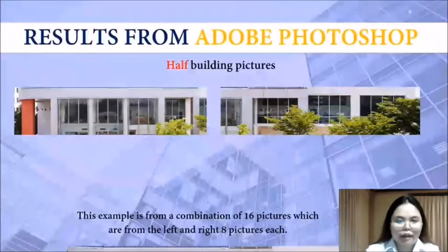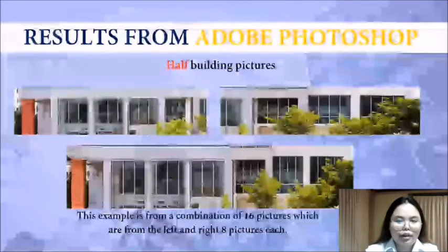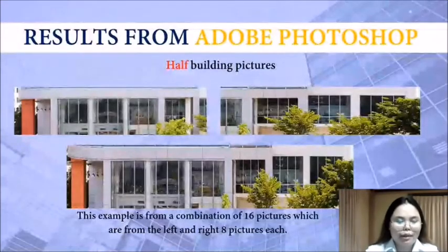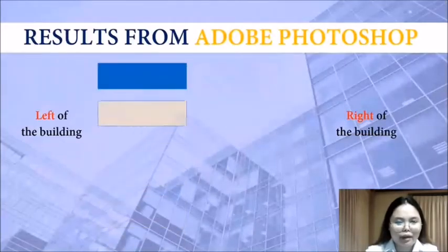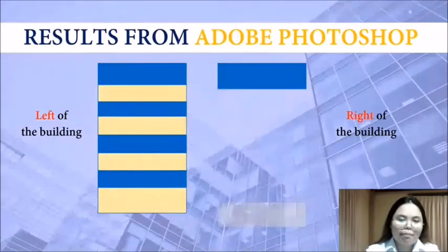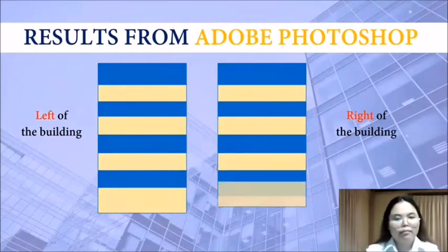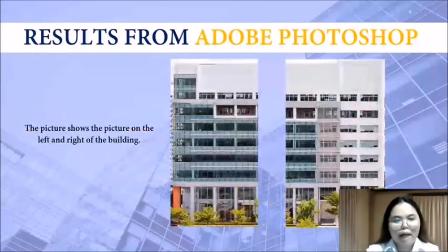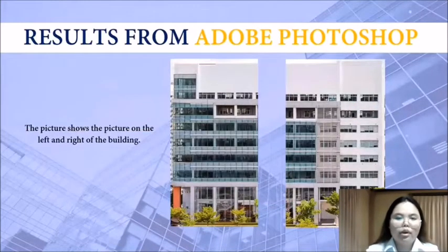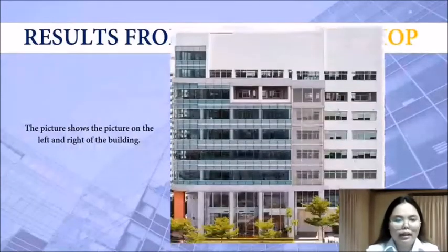This is the result from half inspection, where the UAV took 16 photos to produce the half inspection facade, from a distance of 22 meters from the building. The image overlapping of half inspection is approximately 40 to 60% as planned. After overlapping in the horizontal, two sets of photos are merged in the vertical. These are the results from the half inspection process.